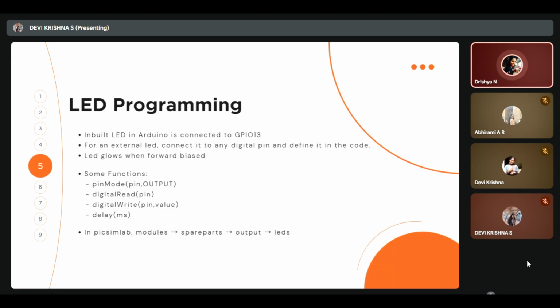The last step is encoding, or digital encoding. Each quantized level is represented by a binary code which the digital system can use. If we are having an 8-bit ADC, the digital values range from 0 to 255. For the Arduino, the built-in ADC is 10-bit resolution. So the digital output ranges from the values 0 to 1023.